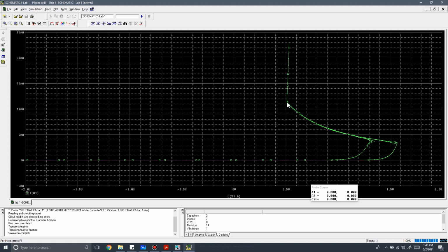Click on the point that we want. So this is the point that we think the holding current is at. So select that point. Okay, and then it will show you that value, right? So probe cursor is equal to 511.211, 11.395. So we want the y-axis variable, which is 11.395 milliampere, right?